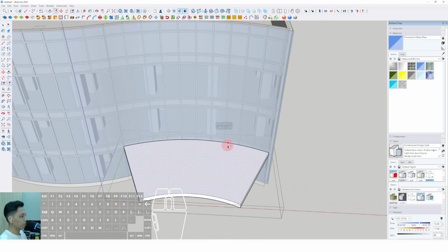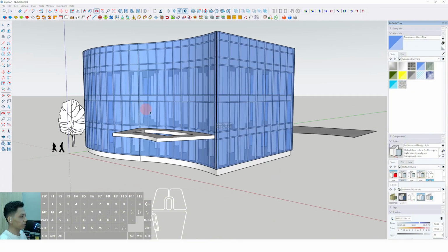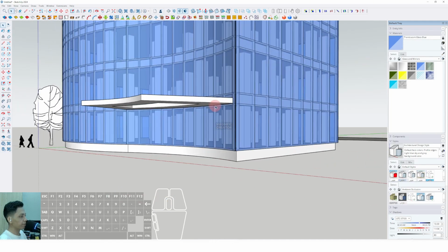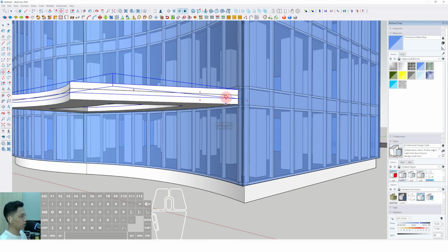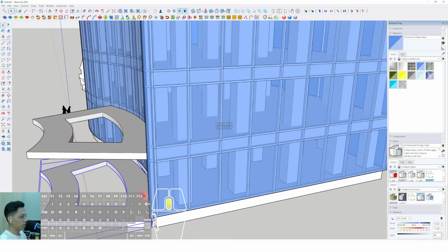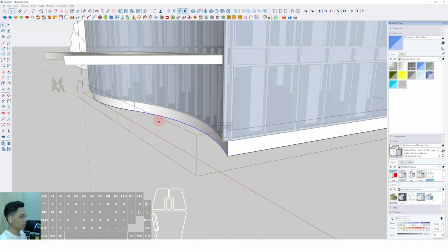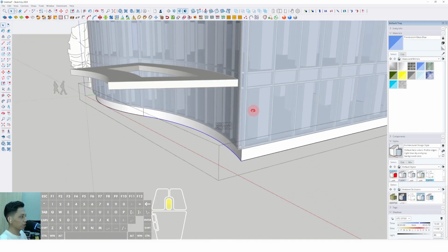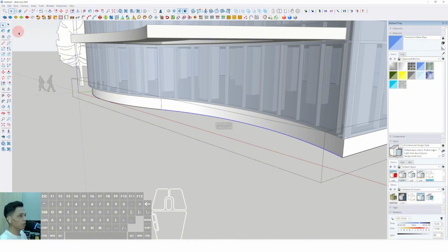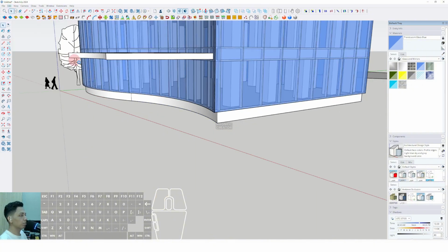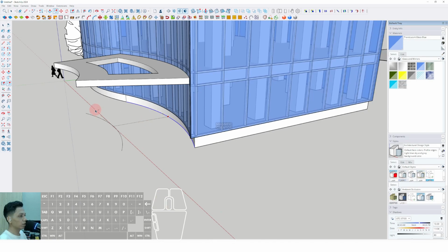And we can also make a canopy in here, or make a larger glazing canopy in here. And you can also move and duplicate this one to this position. We can click this floor, and we can edit, copy, exit from the group, and edit, paste in place, and offset it outside until 7 meter approximately.